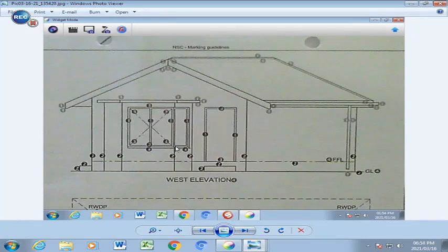And then you will find that you will have that little piece that goes up in line with that, and it links up with the roof pitch, and it goes that way, and this links up with the roof pitch from the floor plan, and it goes down at 30 degrees. Remember to put in double lines here, which is 1 millimeter apart. Don't forget the downpipe. That's brought down from the front of the house where you have the rainwater downpipe, and then the little trap, which is a circle.